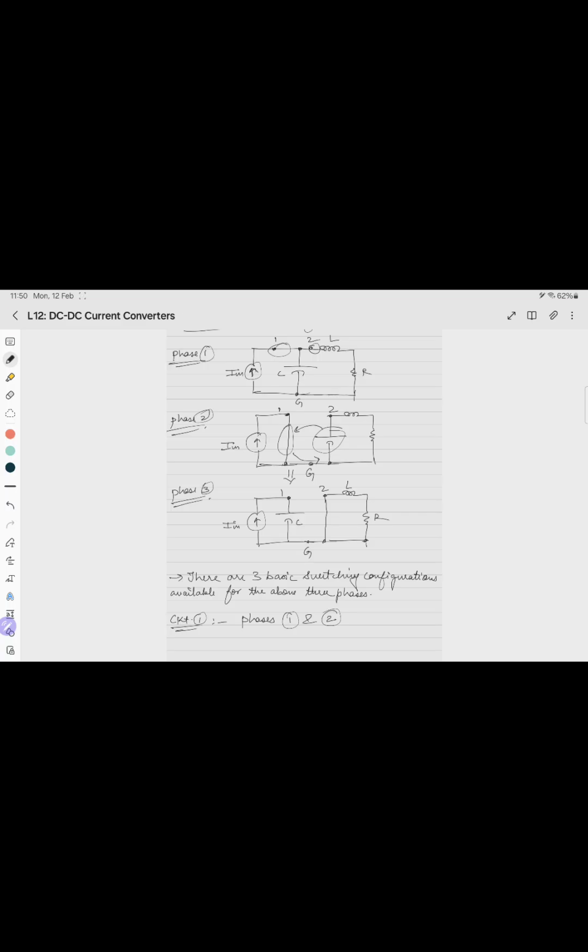So phase 1 says that the capacitor is connected in parallel between 1 and 2, sorry, connected to both 1 and 2 nodes. In the second phase it is connected only between 2 and G, which means that one node of the capacitor is always connected to the node number 2. So one switch is needed between 1 and 2 to separate phase 1 and phase 2, and the other switch should be this short circuit.